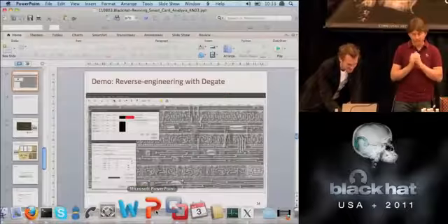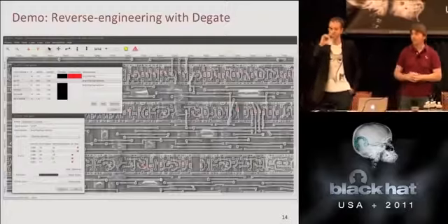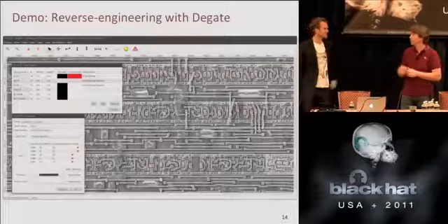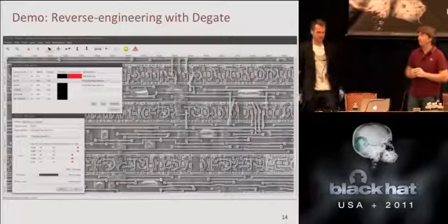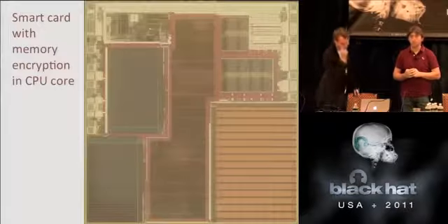The gentleman in the rear asked the question: tracing out where you want to focus on because it's so large today and it's just a sea of gates. There's glue logic everywhere, and follow the ROM really and look for flip flops. Right. Look for chain flip-flops in the big, what we call glue logic. So this type of a chip.